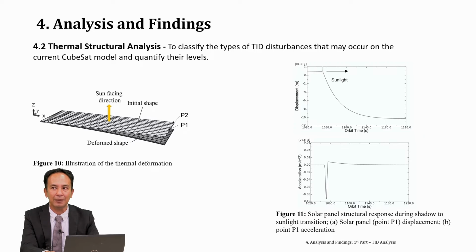due to the change of heat absorbed along the orbit trajectory, the temperature of the solar panel varies accordingly. In the shadow region, the entire solar panel structure is almost at the same temperature, and then changes occur when they enter the sunlight, as their temperature will increase differently depending on the position of layers and material properties.